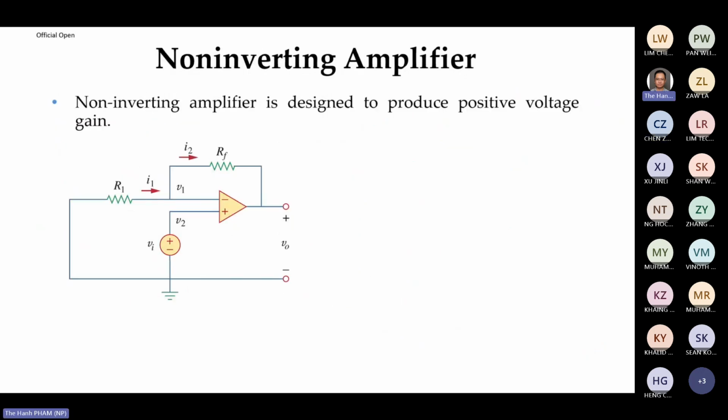Then you have a non-inverting amplifier, right? So for the non-inverting amplifier, I think I just give you the formula, because Vo is 1 plus RF over RI times Vi, right? And by the way, this one is a good one because the input impedance is very high. Input impedance is very high. No current running here.